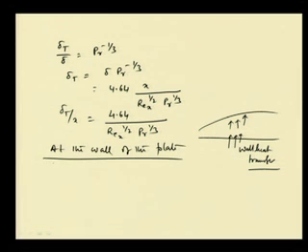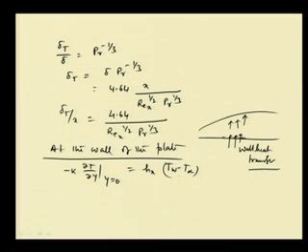The wall heat transfer is happening due to conduction, so at the wall, minus k into del T by del y at y equals 0, the conductive heat loss from the wall to the fluid in the near vicinity layer, is equal to the convective heat loss, which is defined as h x into T w minus T infinity. This is Newton's law of cooling, and the other is Fourier's law of thermal diffusion.